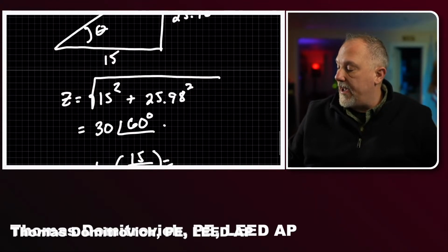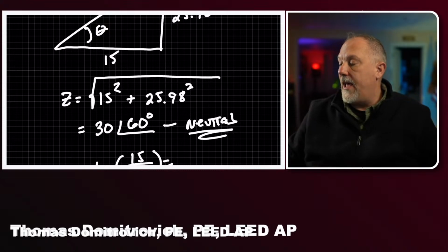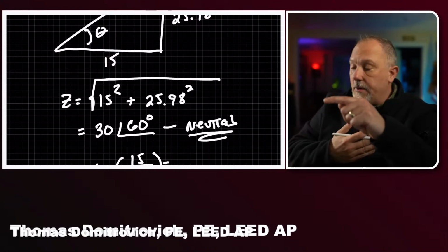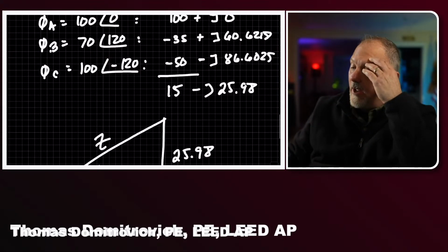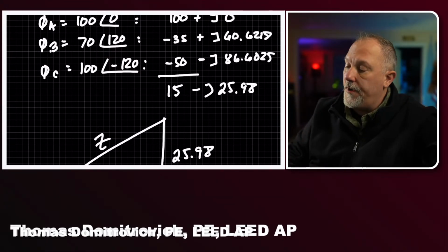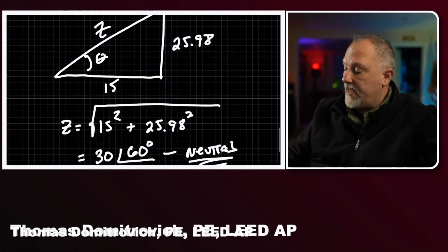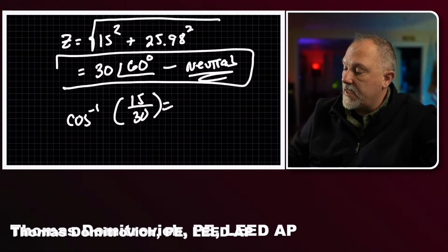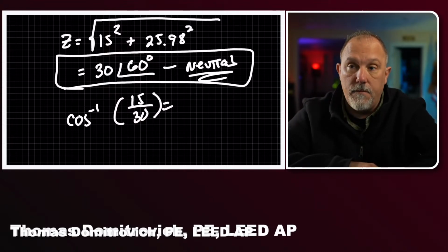So that's what I have in my neutral. When I have an unbalanced load, I have 100 amps going out at 120 degrees phase angle difference. I only have 70 going out on phase 3, and my difference is 30 at an angle of 60 coming back over the neutral.